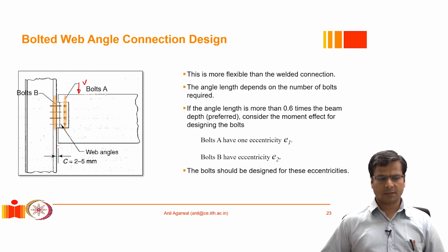Also, as we had discussed, when the beam starts to rotate because of the external loads, because of that rotation also, you will observe that there will be an additional shear force demand on these bolts. The top bolts will be pulled outward and the bottom bolts will be pushed inward. Okay, and that will introduce an additional force demand on these bolts.